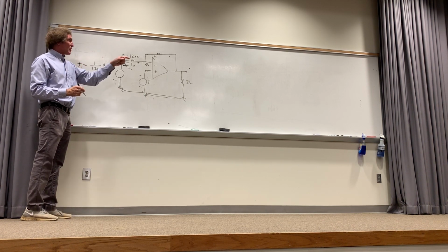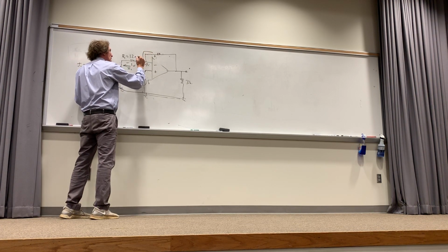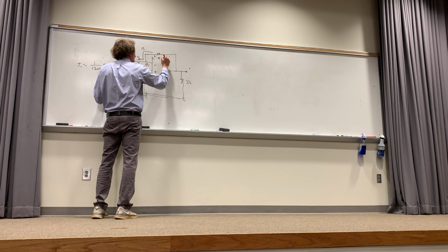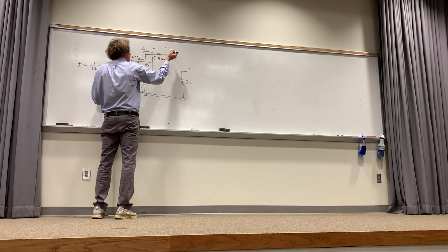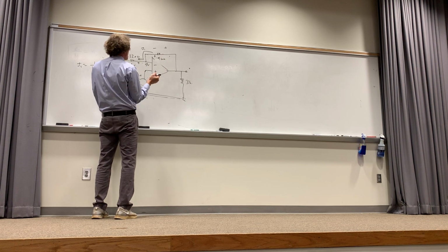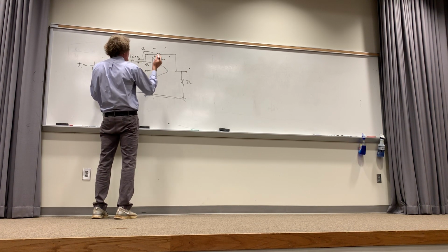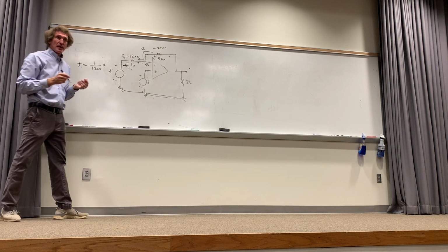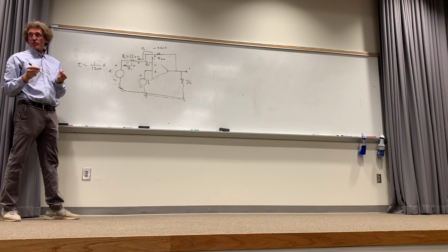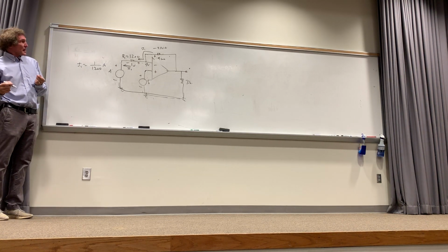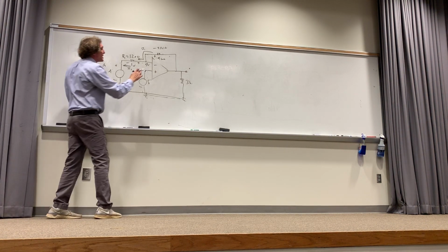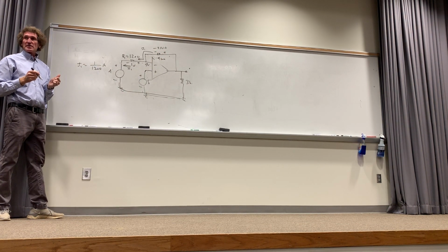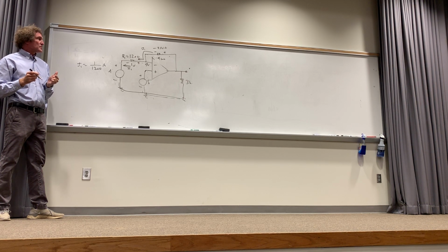Now that current would flow here as well. And if that's I1, this was 4200, right? That would make this plus or minus I1 times 4200, or 1 over 1200 times 4200, or 3.5 volts. Correct, class? You with me? I'm just reversing. Now notice it's going to be plus to minus, right? Look at the direction of current. Correct, class?